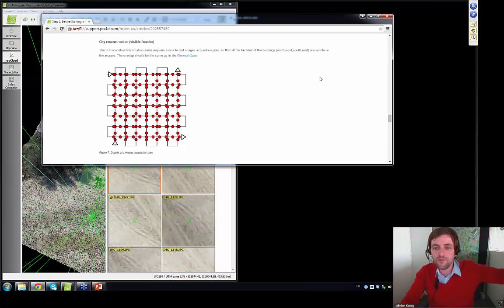By having the drone follow the altitude of the terrain, you will ensure that the overlap is consistent even without changing the capture rate of the images. This way you will have the most uniform overlap in the whole project, and that is a good key to having a successful project. So yes, it is definitely recommended to change altitude while flying over a mountain.